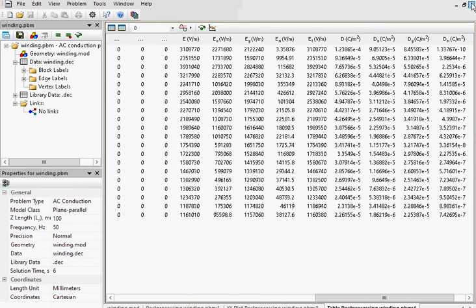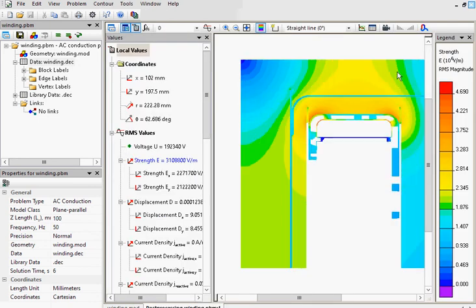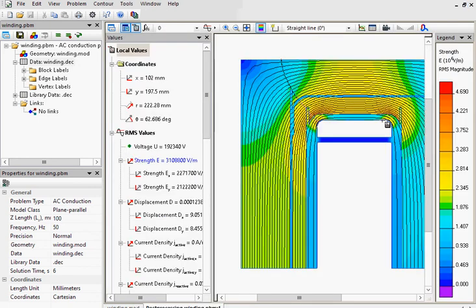Okay, we have completed the analysis of this configuration of the end winding insulation, and we have located some hot spots which you would like to eliminate. It's easy, you can modify the geometry model in QuickField. In fact, the angular ring should follow the electric potential lines. So maybe I need to move this pressboard a bit higher.